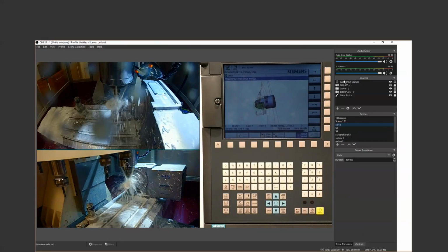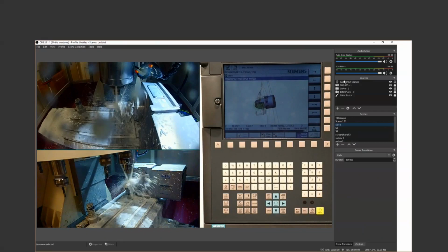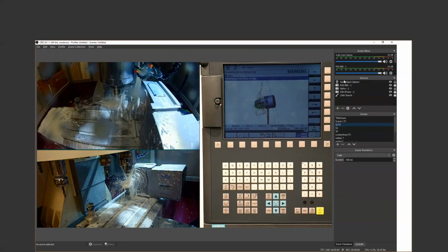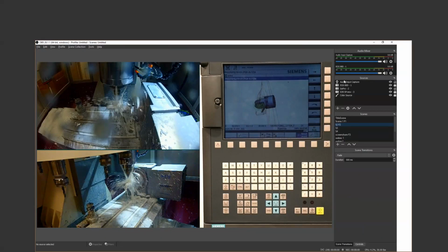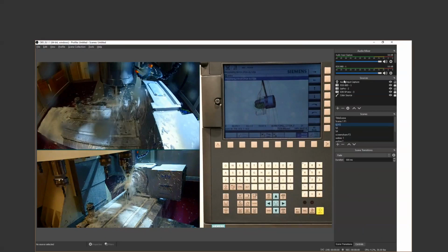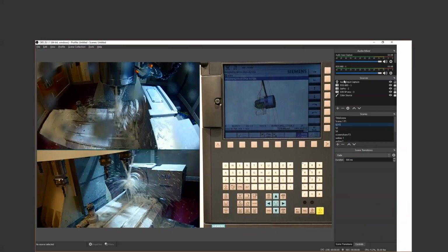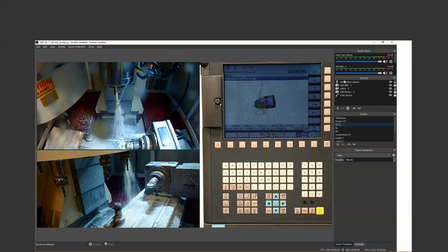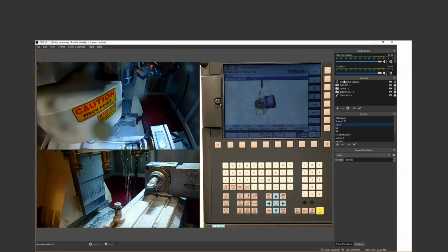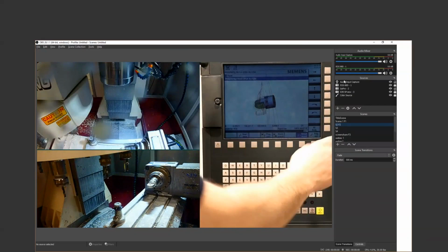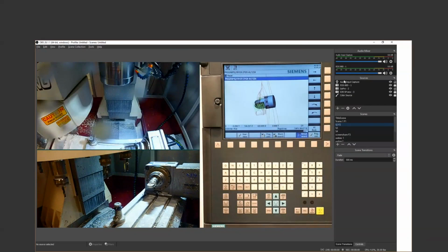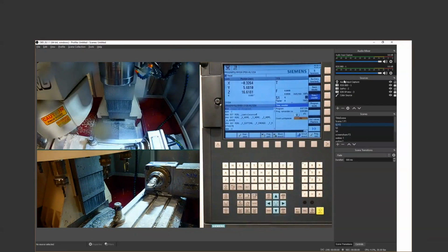And once again, the geometry drove the tool axis, not construction coordinate systems. I think that is so cool, the way you can just pick some common features on all kinds of different planes. Didn't have to jump through all kinds of hoops, making new planes on each point. It was very cool. And there we go. Really, we got a part. Really speeds up your programming time when you don't have to put a lot of construction geometry into your part file. Absolutely.